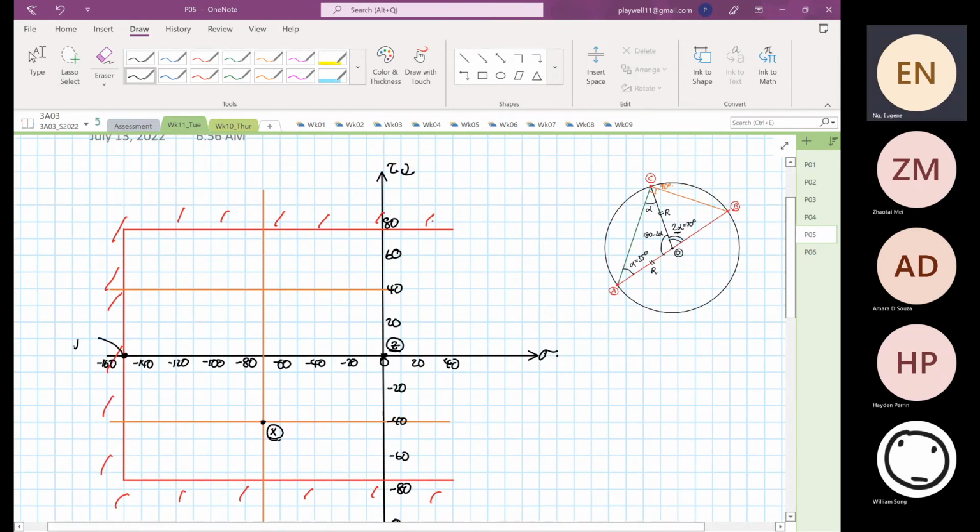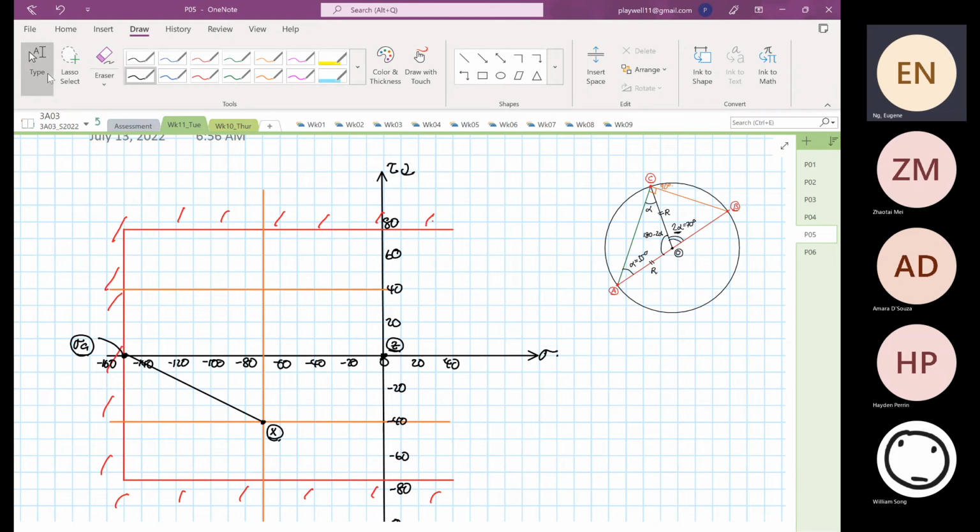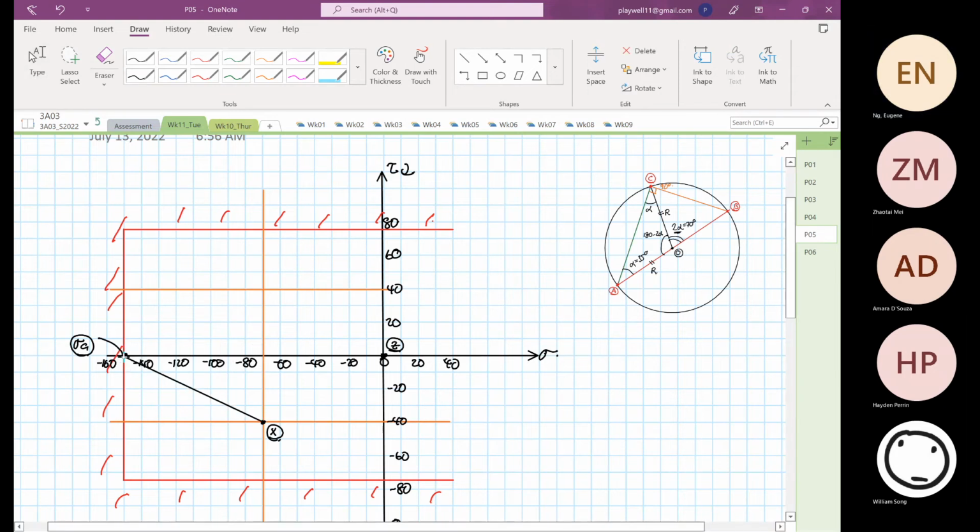And this is our stress A, right? That's our principal stress. It has to be at that point at minus 150. It cannot be greater than that. Okay. So now I'm going to draw stress mean, or stress A to point X. Now, point A is not my average stress. I want you to watch. Point A is not our average stress.